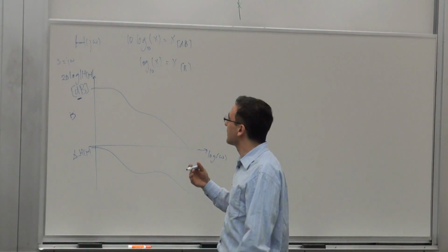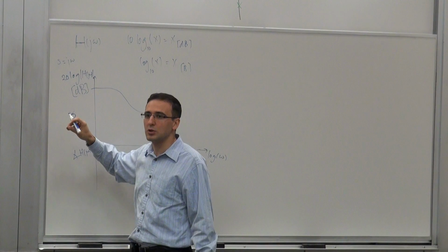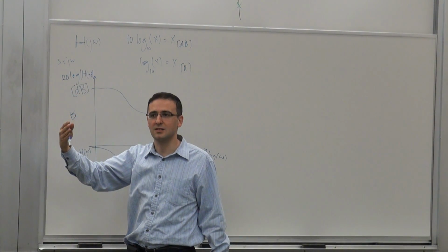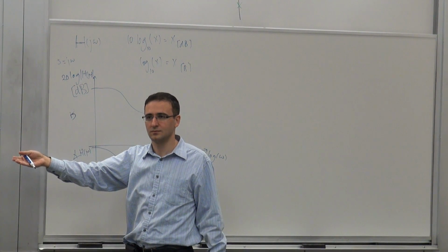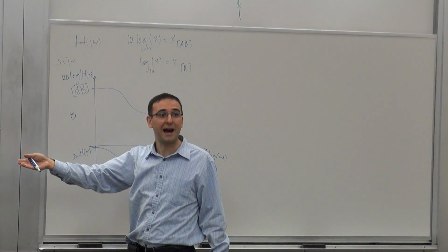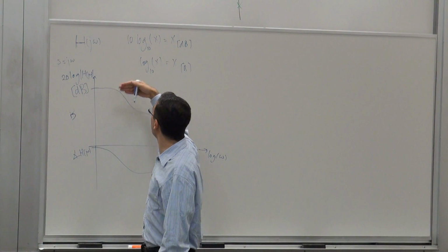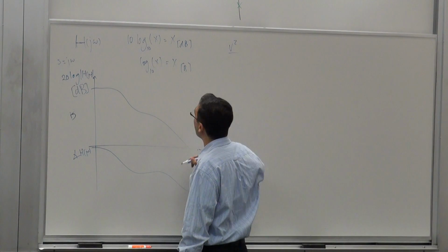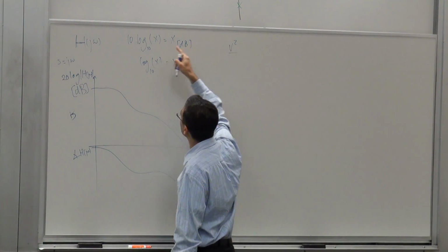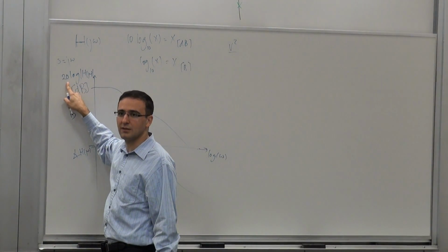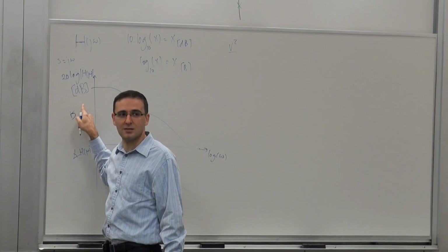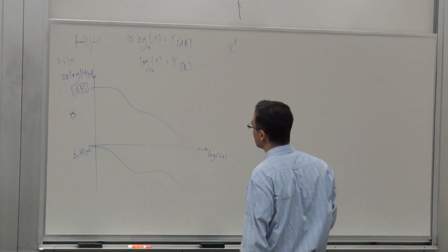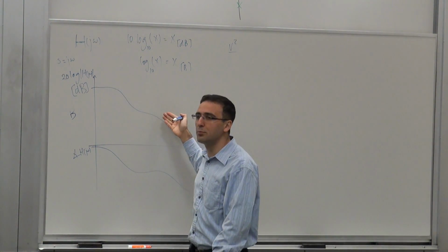Now, if you're dealing with voltages or currents, to get the power, if you have a voltage, let's say V, across a resistor, the power across that resistor is V squared over R, the instantaneous power. So you have a factor of 2. To get to the power, you have to have V squared. So that square comes back and makes this 20 log. So whenever you're dealing with voltages and currents, if you write it this way, it's on the same scale as the power. Basically, this is called a Bode plot.